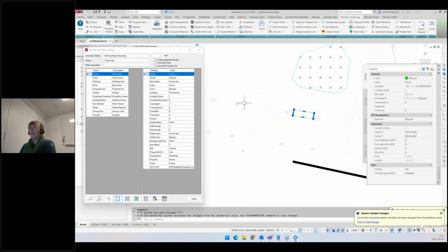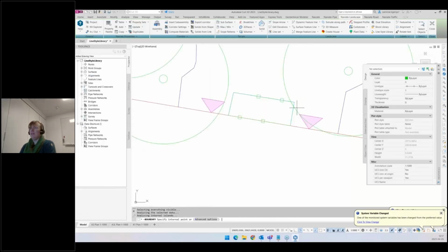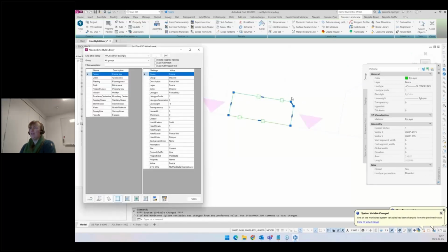Be aware though, if you use this on objects, if you feel like, well, I want this square as well to be a B poly, what's going to happen here is it's actually finding a little corner there from another line. So it's analyzing the line work that it finds in your file and creating the B poly from it. So sometimes there might be lines that you just ignore, but B poly finds them. So be aware that this will happen. This is perfectly normal for the command. But it's a normal polyline, so you can edit it how you would like once it's been created.